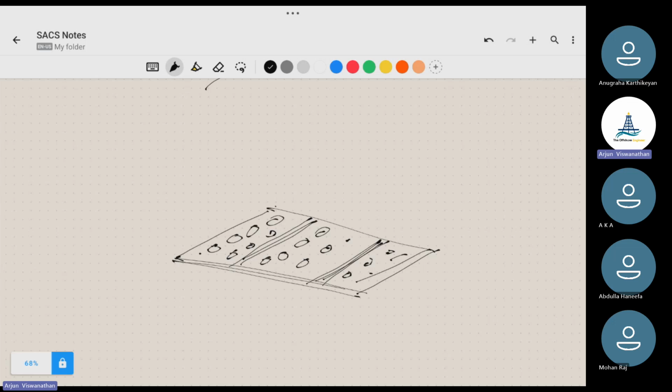This will make sure our structure does not get penetrated deep into the seabed, because the soil is very loose. The structure needs to stay there, and that's why we provide a mat for stability. Then there is the top structure. On top of the foundation, there will be a top structure. This top structure will have different functions according to the type of structure.